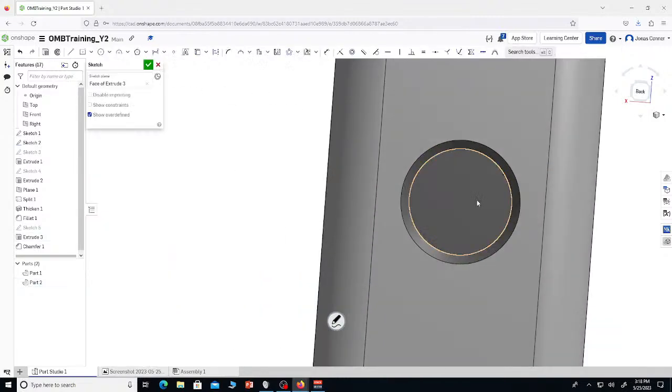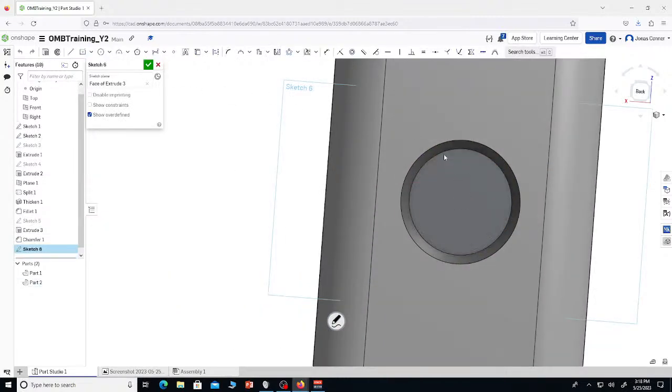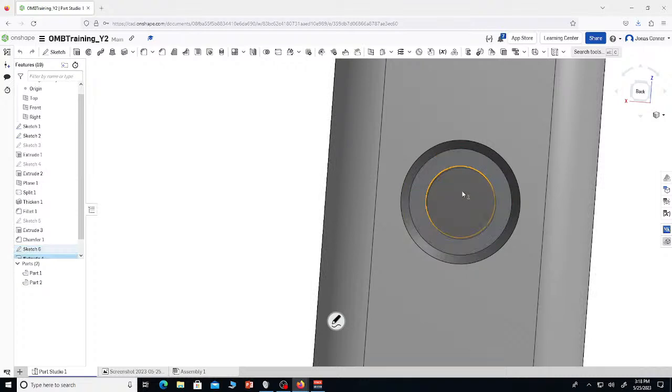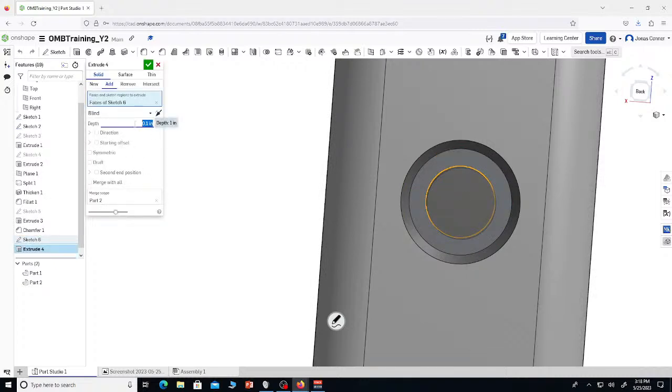And then we'll use draft right now. Like I said, draft is pretty good for decorative things. So I can extrude this by like 0.1 and then draft it by like 30 degrees inward. We'll set that more like 60 inward. Nah, we'll set it to 30 or 40. That's good.